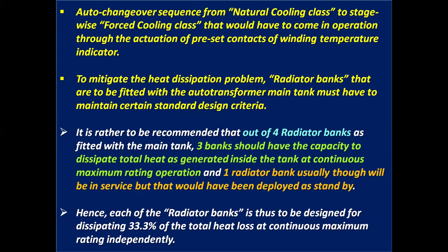Autotransformer, while in auto changeover sequence from natural cooling class to stage-wise forced cooling class, would have to come into operation through the actuation of preset contacts of winding temperature indicator. To mitigate the heat dissipation problem, radiator banks that are to be fitted with the autotransformer main tank must maintain certain standard design criteria.